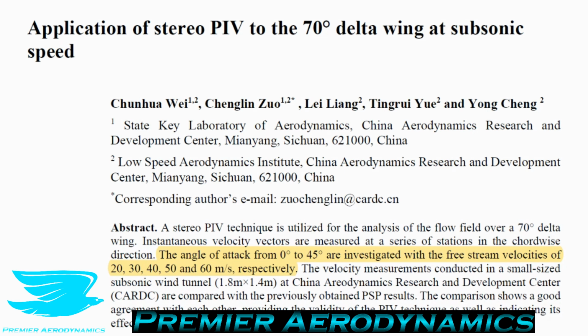So you have this laser sheet, and you have these particles in there, and these particles are being illuminated by the laser. So usually the laser is going to be green. That's one of the most common ones. And these particles are going to shine back this light, and you can take a picture of these particles because they're illuminated now. And then very quickly afterwards, you take another picture. Between those two pictures, you can now see where these particles have moved. And because you have lots of particles in the flow, you can get a very good idea as to what the flow is doing, where there is vorticity, if there are vortices, flow separation, all different stuff.